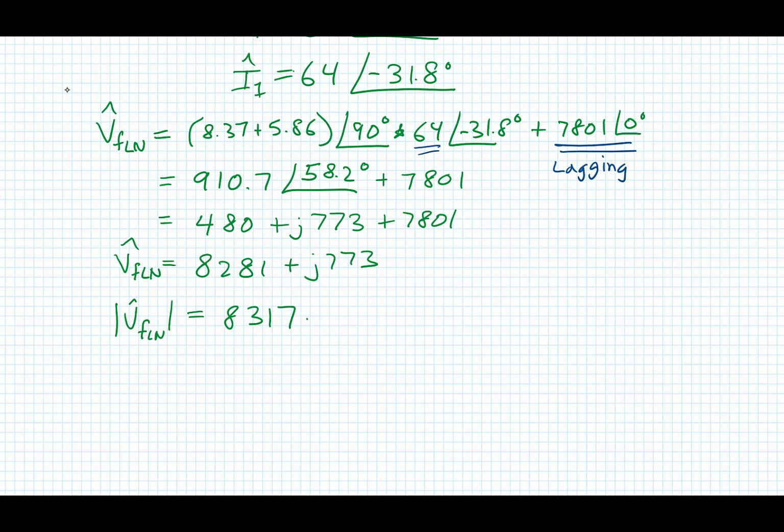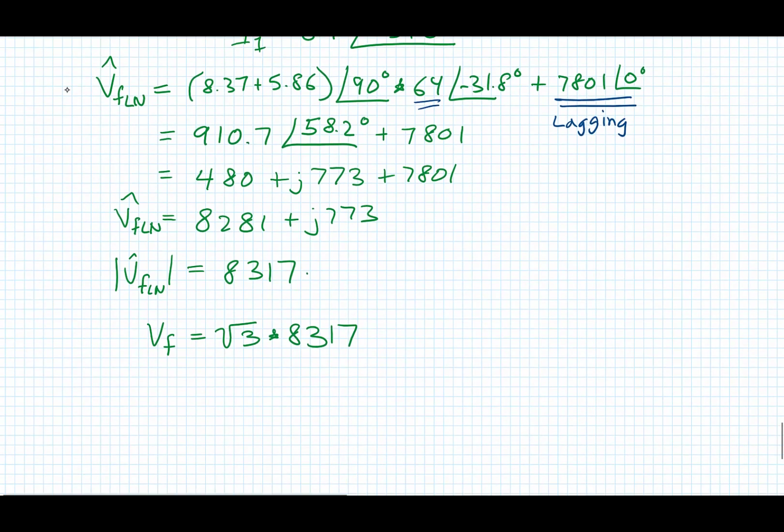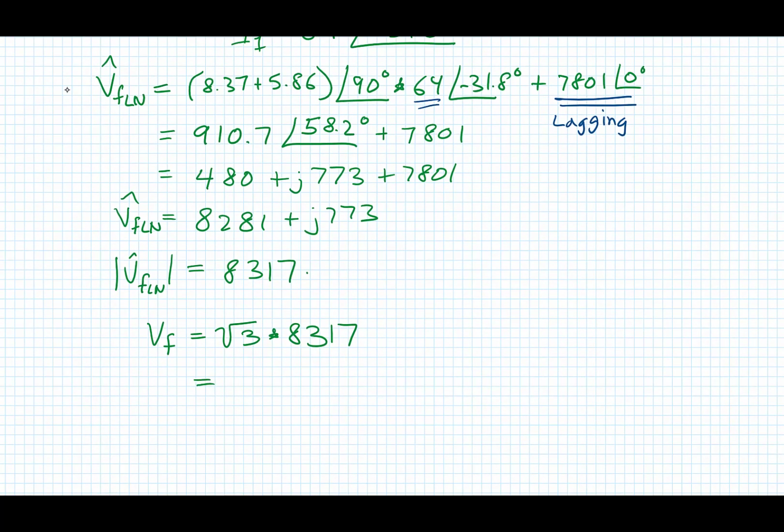8317. But that isn't our final answer, is it? The V feeder voltage that we're looking for is going to be square root of 3 times that number. And so what is that? It's 14.4 kV.